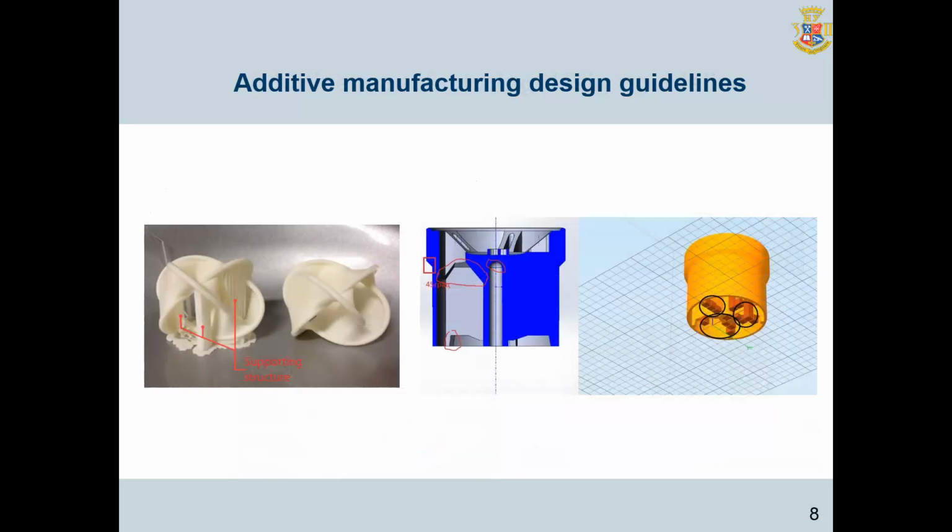Each overhanging element requires a supporting structure. The fewer overhangs, the fewer supports you need, the less material and printing time you need to spend on them, and the cheaper it will be to print. It is allowed to print without support walls which have an inclination angle of not more than 70 degrees. Sometimes it makes sense to create artificial support in the model itself.